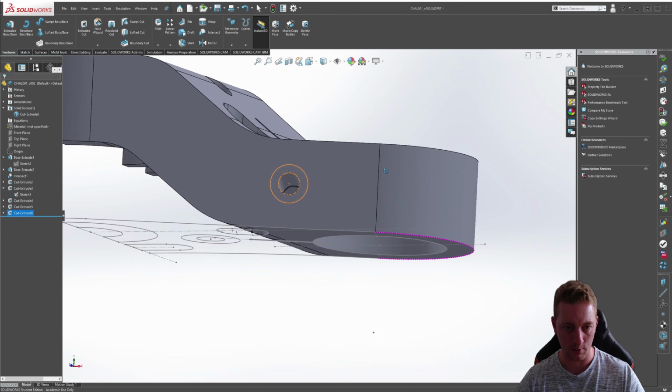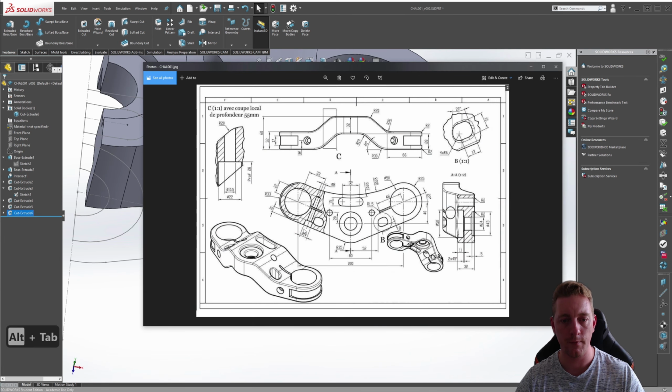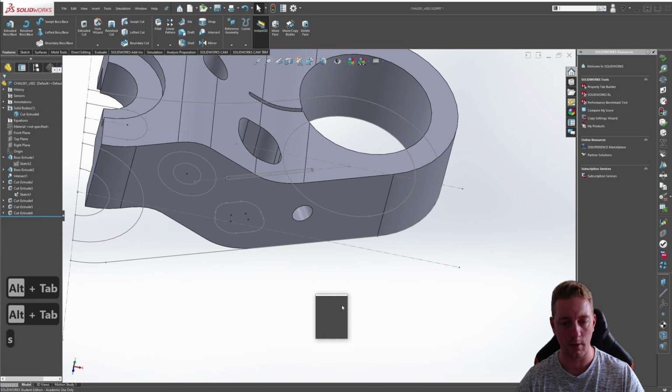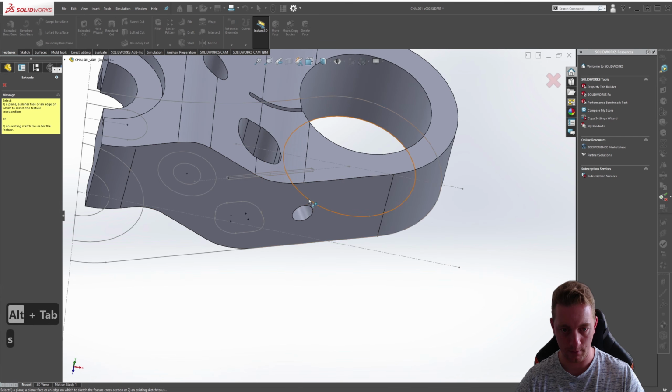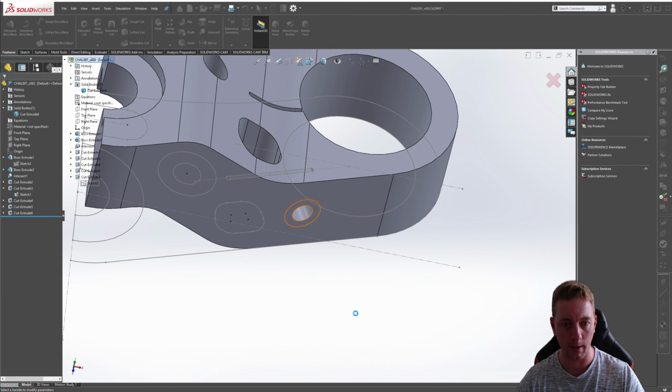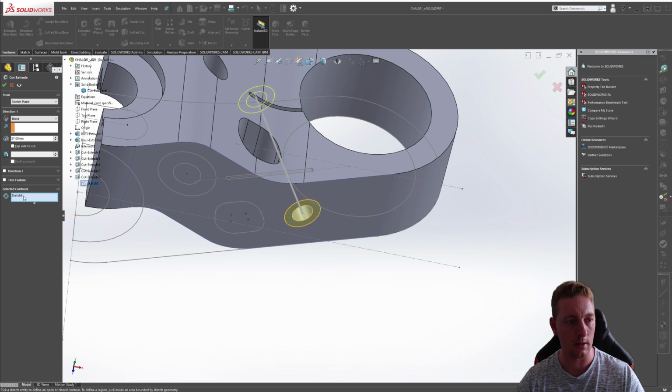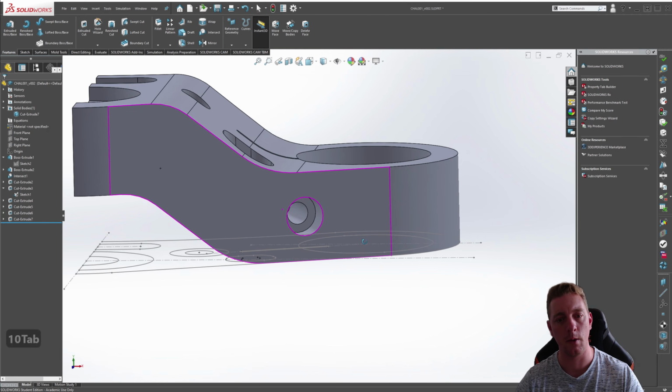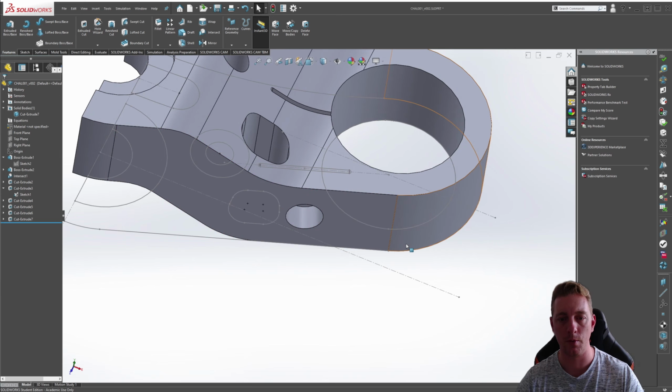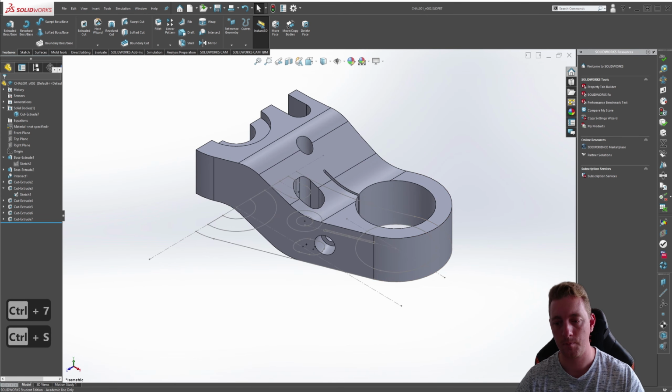And that's going to cut it all the way through. And then the final one is 10. So this is another cut, reusing the same sketch. You might have to expand the menu. We can clear these contours, and we want the outside one, and we make that 10. And there we have our drilled hole through that side.